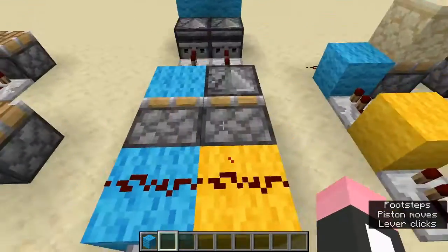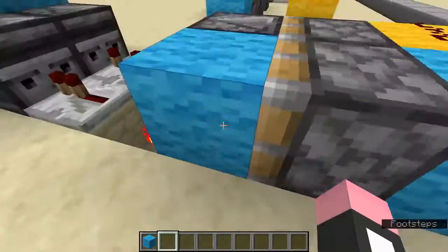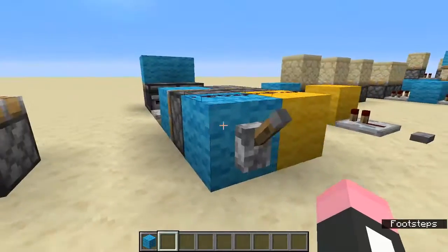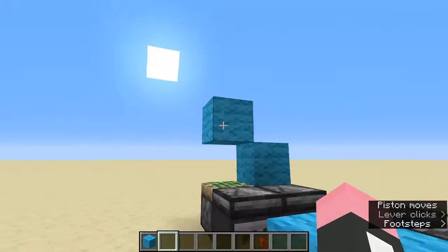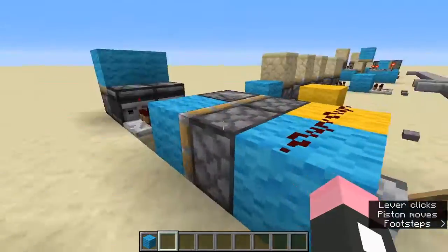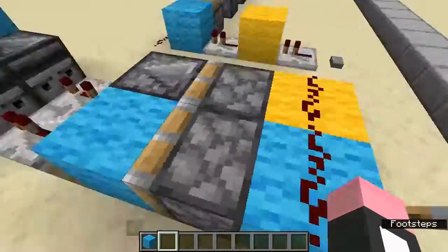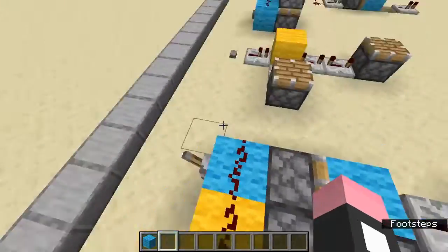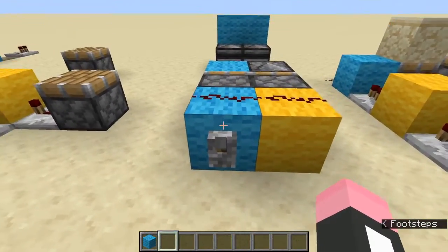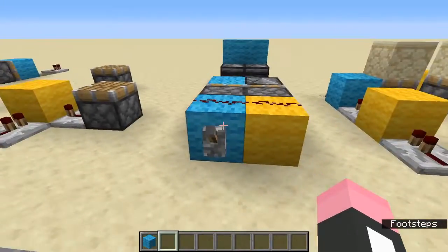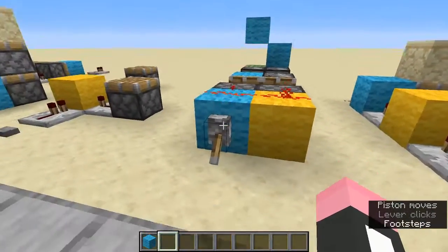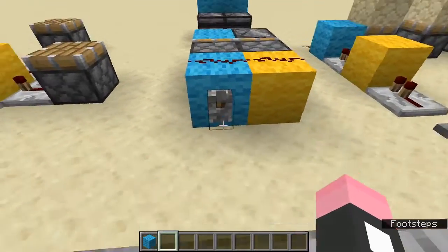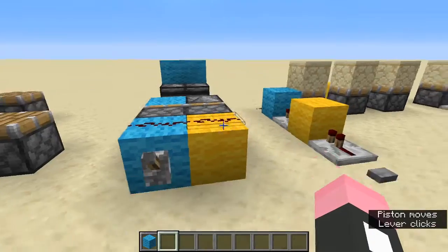And then we compare these two. If we have a constant pulse length, something like this component will activate according to the lever. So if it's activated, then this component's on, and when the lever's deactivated, the component turns off, just like that. However, if it's a monostable circuit, then this only activates on the rising edge of this lever. So when it's activating, it activates twice, but when we deactivate it, it doesn't happen, because we already activated and deactivated it twice, just like that: rising edge, falling edge.